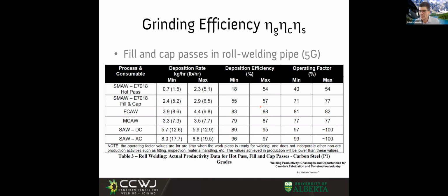Okay, and Wesley is saying something that I didn't know, but you want to grind up part of the joint prep so the electrode comes in. All right. Well, and here we have a comment about removing the slag, that in 6010 typically is easy to remove, but when you do the root pass, the slag gets trapped at the toe of the weld, the root pass, that is the toe against the face of the bevel.